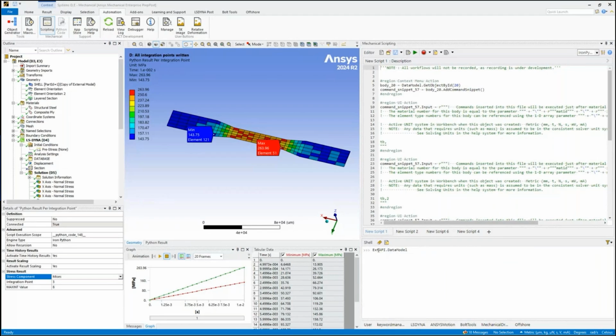So if I want to talk to the data model, the data model is pretty much one of the fundamental ways of interrogating this model. If I do DataModel and then Project, you can see the project up here in the tree is pretty much the same as the name there. So if I do Project, that gives me access to that Python object, which I can then interrogate the model tree with. So if I do Name, for example,